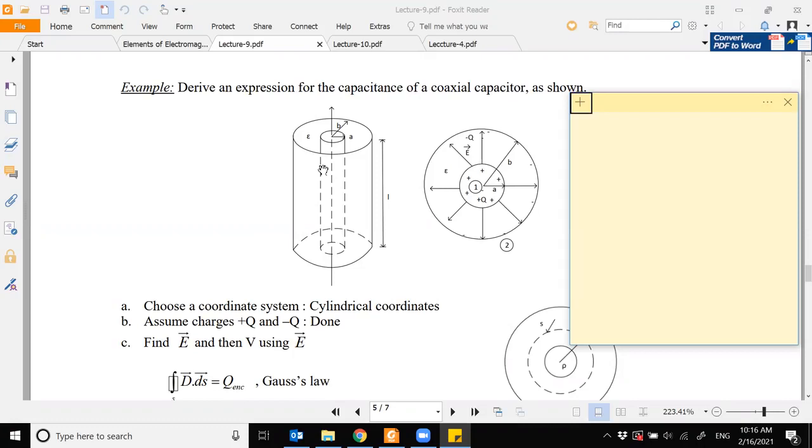So it becomes very important. As engineers, for the coaxial cable, we always want the coaxial cable capacitance to be as small as possible, and the resistance also as small as possible, so that this time constant becomes as small as possible. And this will allow you to take your signal for very long distances.